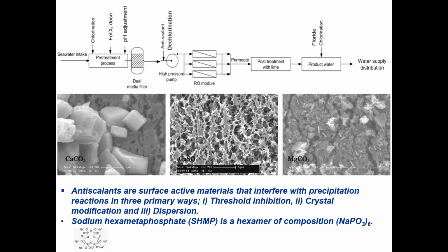And so how can we decide? The dosing of this anti-scalant is just like chlorine dosing, you just mix it. The way we introduce the anti-scalant is after the filtered water, before reverse osmosis, because we expect only water molecules to pass.